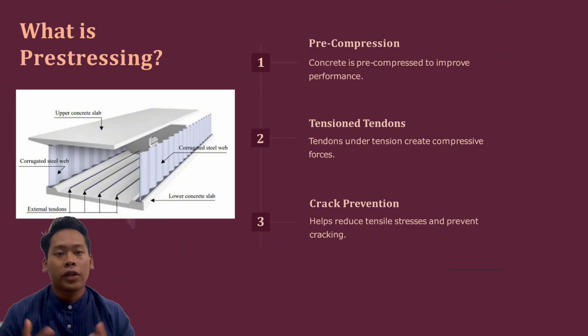So for our introduction, prestressing. Prestressing is a technique used in concrete construction to enhance the performance of concrete structure. Normally, concrete is strong in compression but weak in tension. Prestressing helps address the imbalance by introducing internal forces that counteract the tensile stresses that occur under the load.